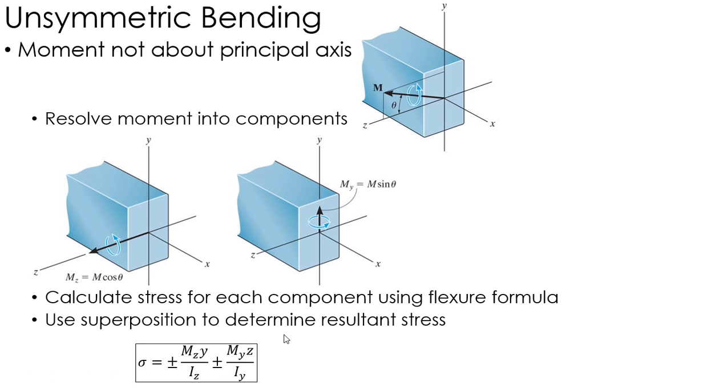I find it just easier to look at the problem and recognize that, for example, this one is in tension, this side is in compression, and on this one the bottom is in tension and the top is in compression. So when you're adding them together, if I'm adding up in this upper right hand corner, you just recognize that it's in compression on each one of them and they're both negative values. So again, it's just a look at the picture, you break it into components, and figure out, based on what part of the beam you're looking at, if you're under compression or tension about either axis.